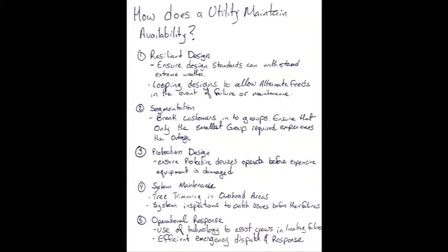Are they putting in a pole that's big enough and strong enough without being so big and so strong that it's expensive for no gain, and heavy and difficult to deal with for no gain? Are they using appropriate tensions so that we can withstand extreme weather conditions? Are we guying properly? If we get an ice storm, is it going to hold up?